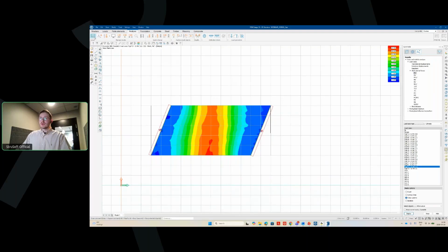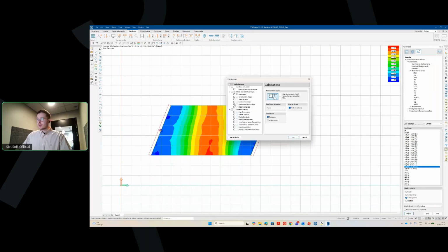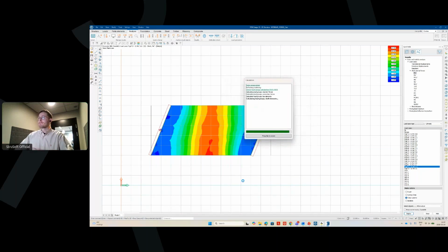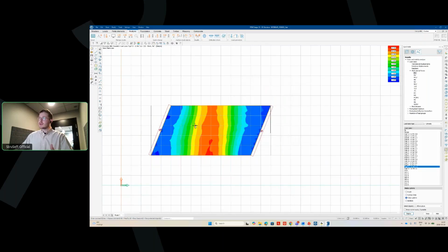Okay, so let's see how long it takes just to add the maximum of load groups. And I think it said something around 1 minute 15 seconds for the load cases. So you can see it is extremely fast, and it is the optimization algorithm doing a lot of work here to combine many combinations, and this is then very useful for bridge engineers, of course. So we'll look at the max of load groups, results, shell internal forces, MX, MX again.